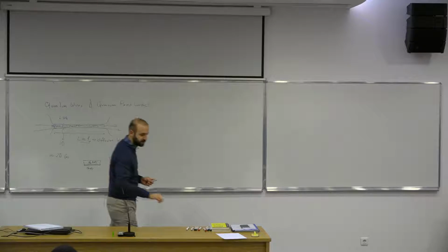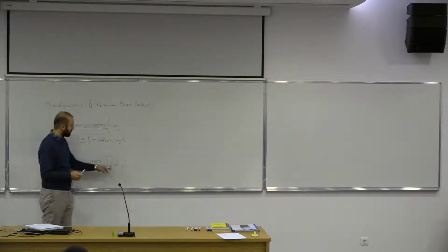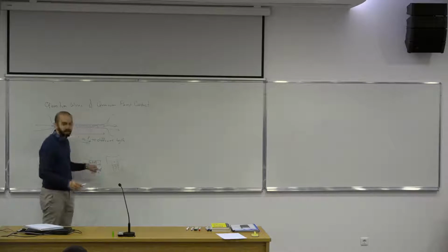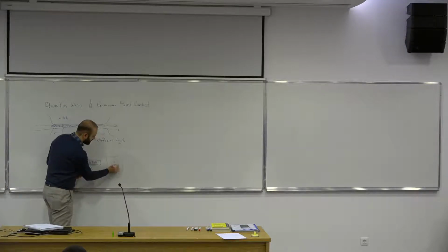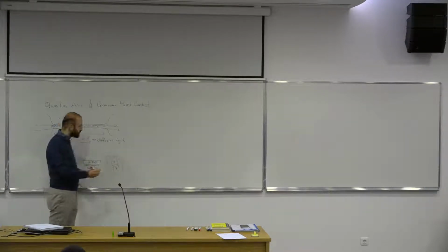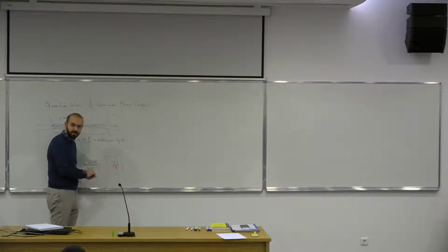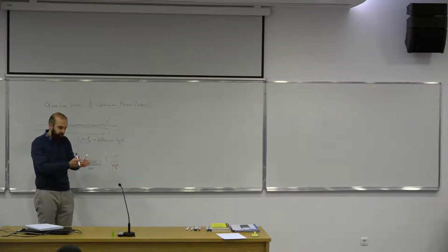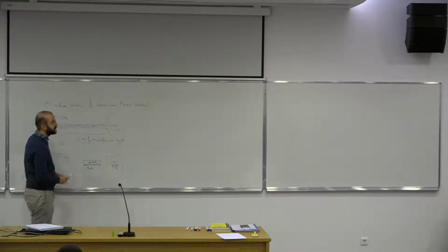And what people do typically is they pattern electrodes like this, okay? And then they apply certain bias to these electrodes, and these are gates that are not in contact with the 2D electron gas. They are resting on insulating material, so they are local gates. And when you apply certain bias, then effectively you deplete electrons underneath these regions, and you end up with a 1D channel. Okay, you bring another confinement from the other direction. What else can we think of?